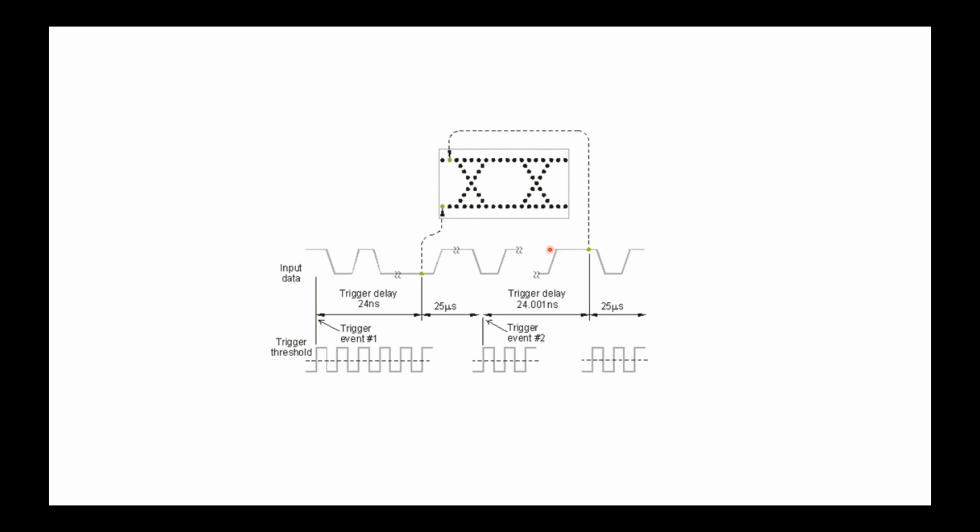And that's the key. And of course, this becomes slower in terms of the data being captured and so on, because you're not capturing in real time. So if you have little events in between, you will completely and utterly miss those events. But that's the price to pay in order to be able to do all the other things this provides.